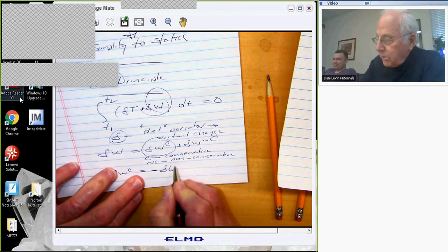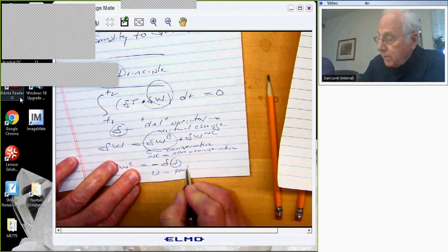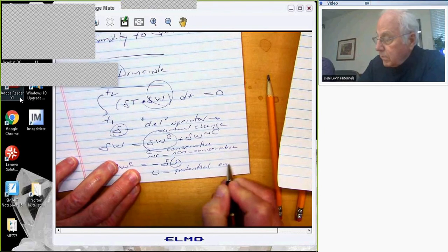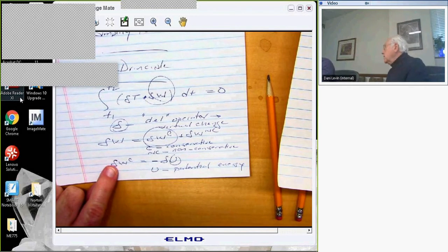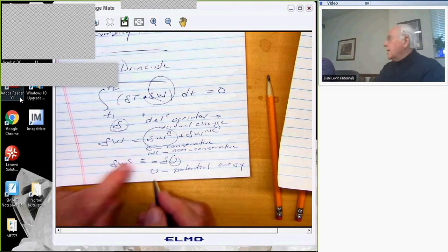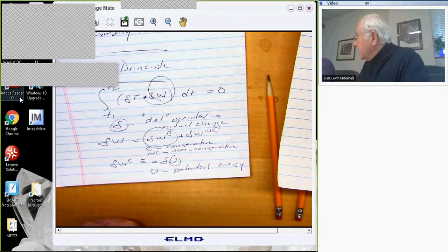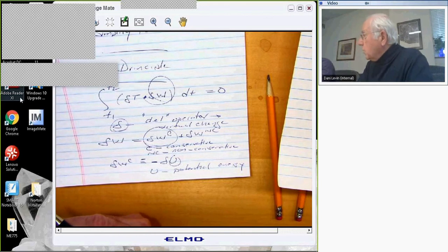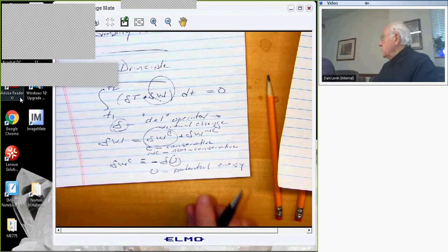Okay, del U, where U is usually called potential energy. How do we compute del U? Well, what we really do, or someone did, is compute del WC. And then, if you will, this is the definition of del U. Using higher mathematics, I can take the minus sign on the other side. Del U is minus del WC. So you compute WC. Normally for elastic structures, someone has already done that and written down the expression for U or del WC, and we'll look at those.